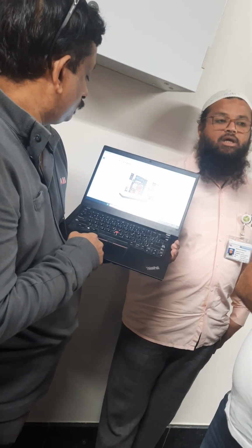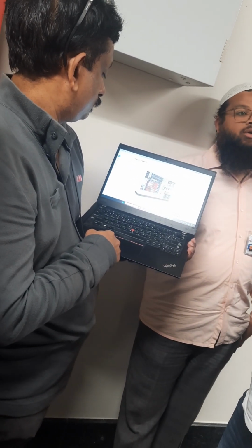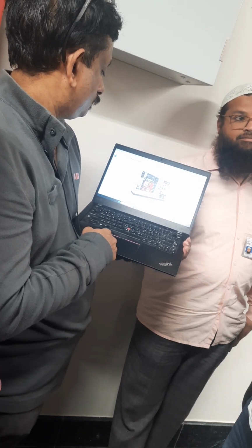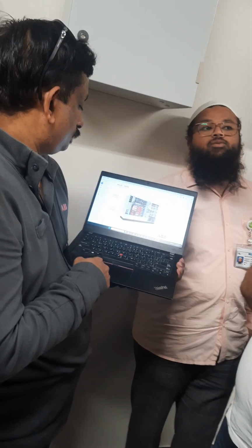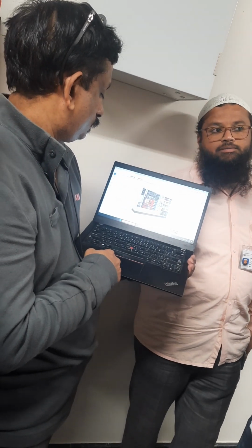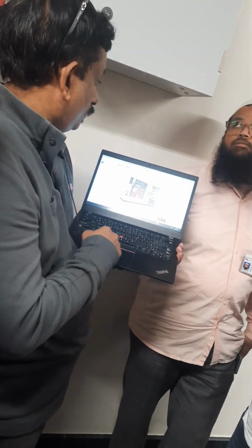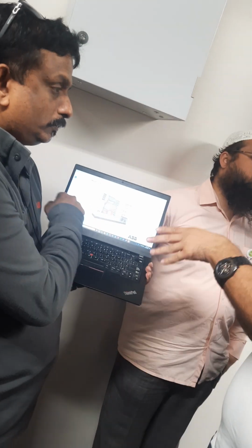Three AHUs, so duty standby or all duty? Two duty, one standby. Okay, so we have a standby. For this room we are maintaining 18 to 22 degrees. Two duty, one standby. There is a filter here, and everything is running.